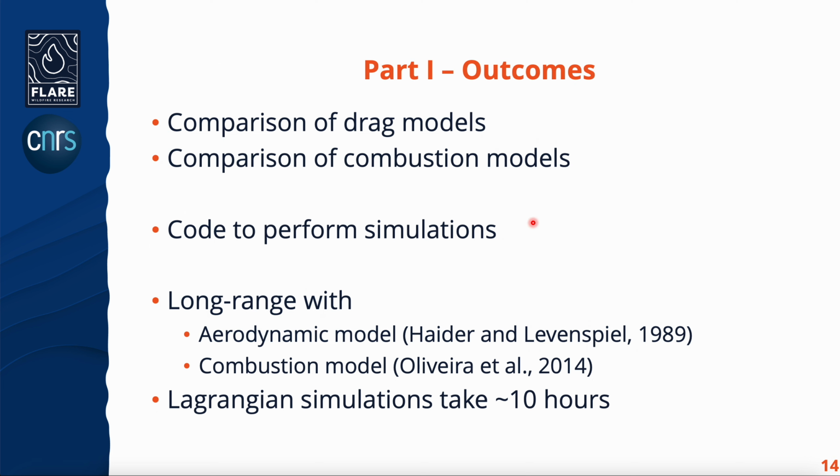So in this first part, we have been able to compare different drag models, different combustion models. We have provided as well the code to perform the simulations. And we have observed that the long-range behavior is best reproduced with these two models, aerodynamic and combustion models. However, an important thing to note is that these kind of simulations where we have around 60,000 particles takes us